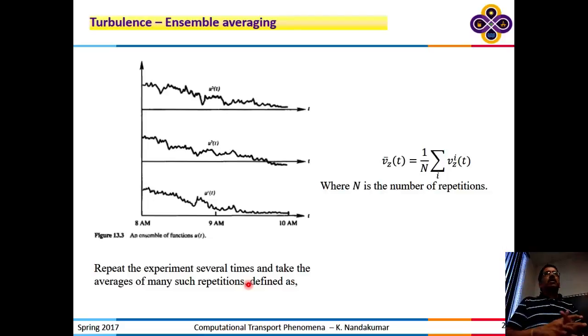So all turbulence models have the need to come up with additional expressions. And you call them turbulent viscosity, you call them by different terminologies. And they can be informed by experiments. So in that you can do repeated experiments, and that data can be ensemble averaged to get the data that you need for the closure relationship. So these days, you can also do them through DNS. DNS to me is an alternate way of supplementing experimental data. Okay, but you cannot do it on a grand scale, you have to do it in a small scale domain.